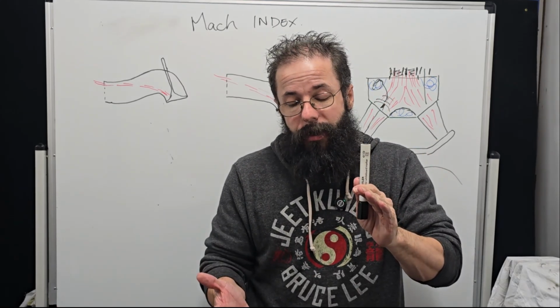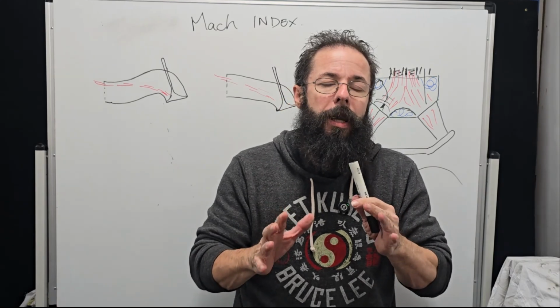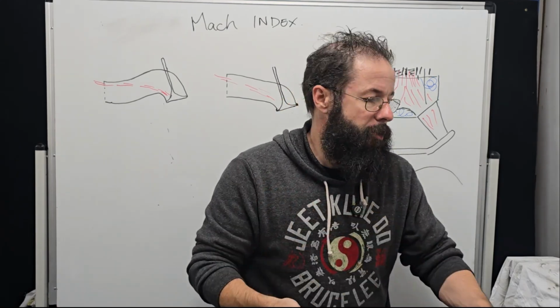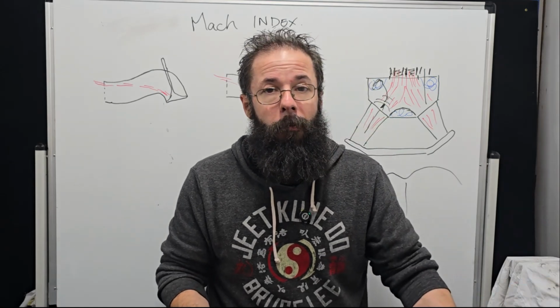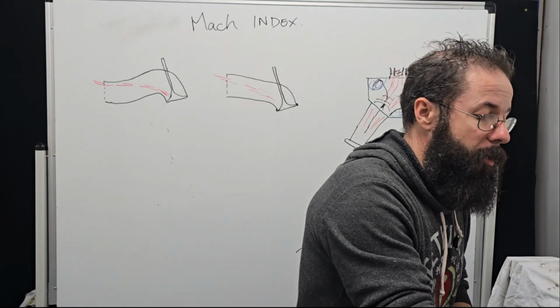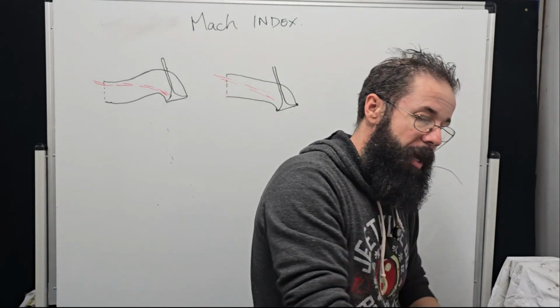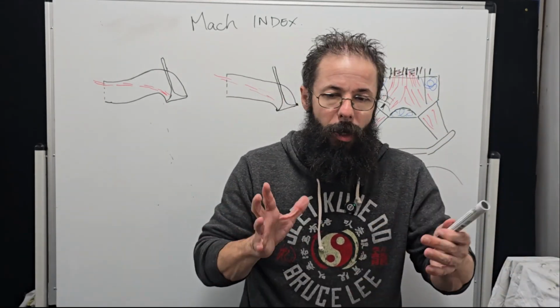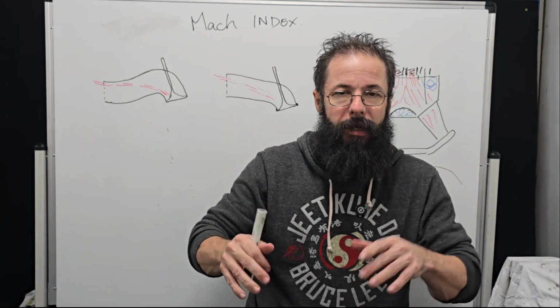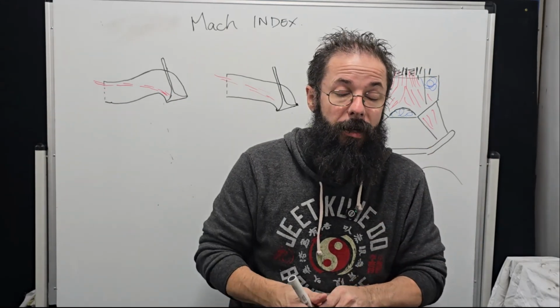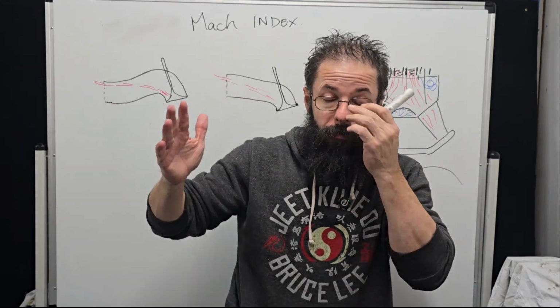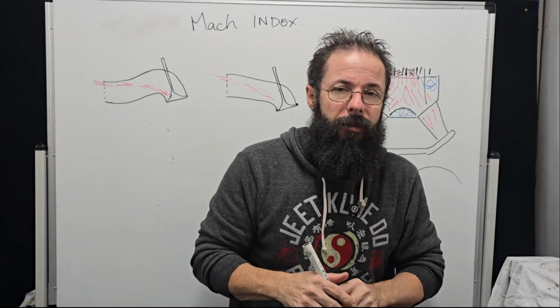And because ITBs aren't a common plenum, they can't soften this effect. When we get it in a common plenum, one runner can compensate for the other. This one has a high pressure wave coming out, which can help fill another runner, and so on. So this is why common plenums tend to make better peak numbers and better horsepower, in the range that we're sort of targeting.